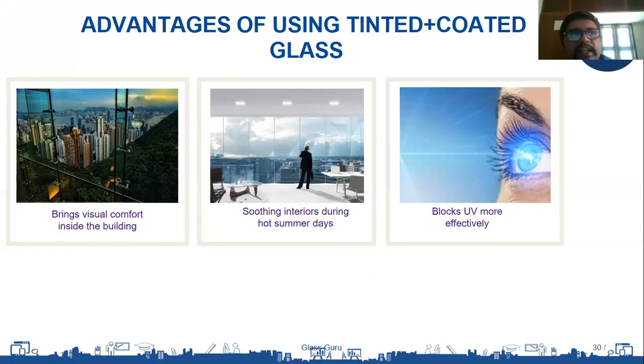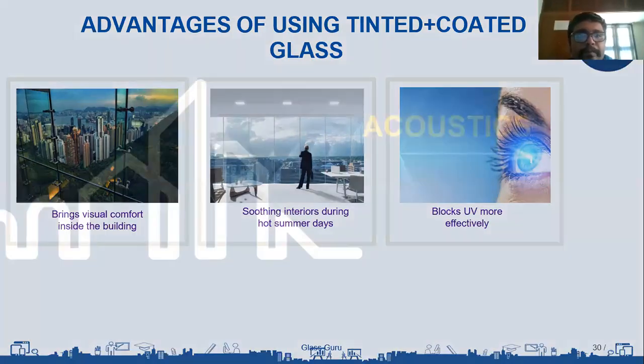If you have a dark gray sofa fabric when you purchase it, it will start becoming light gray over some 7-8 years. When you use a coating done on tinted glass or laminated glass with coating, this actually reduces the UV transmission. So this is another way to reduce the UV transmission, which will delay this process of color degradation of fabric. This is another additional info.